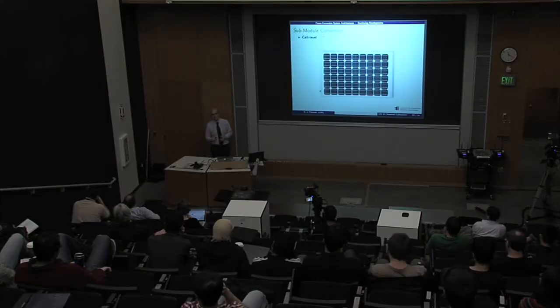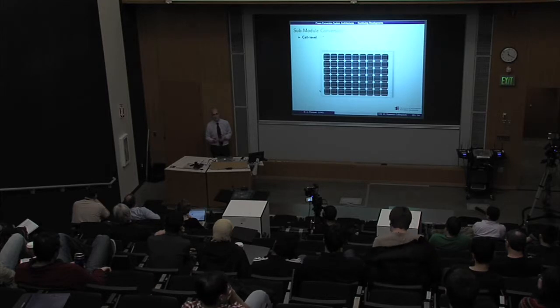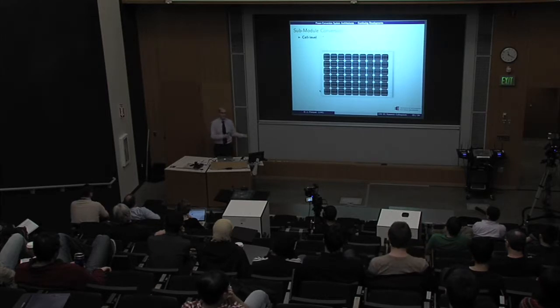So certainly that's less. But the energy capture that it can get is larger, and so ultimately it still ends up having a higher captured energy. As you go down to substring levels, you end up with other issues. The DC optimizers, the DC-DC converter, maybe it's 99% efficient. Okay, now you connect it to a 98% efficient centralized inverter, and now those cascade, and now you're back down to what you would have if you just had microinverters.